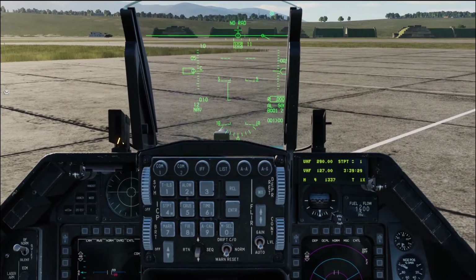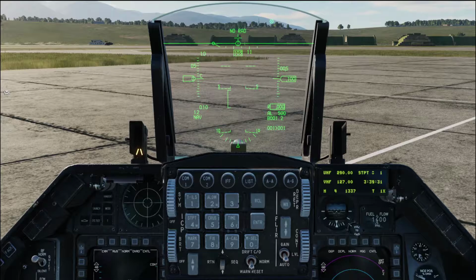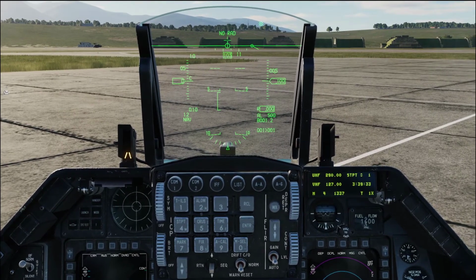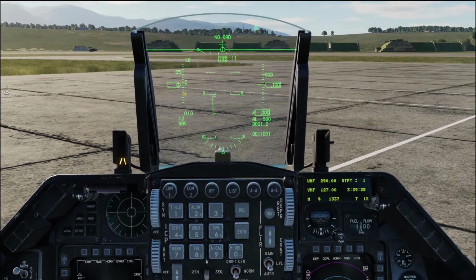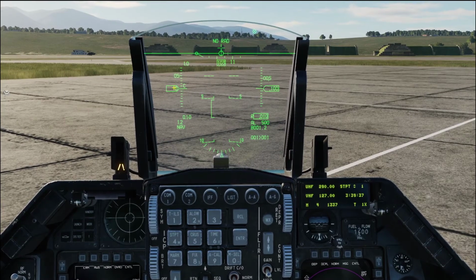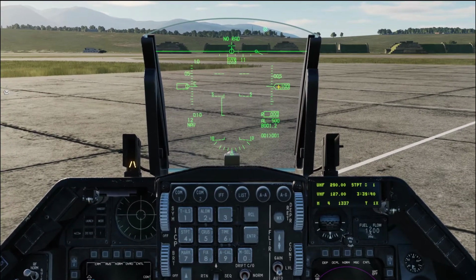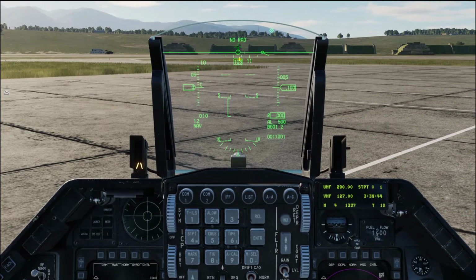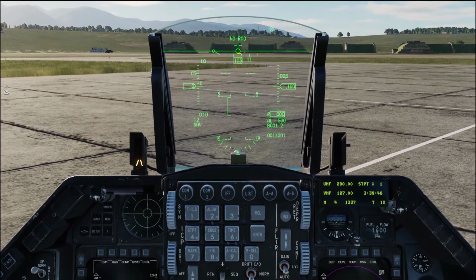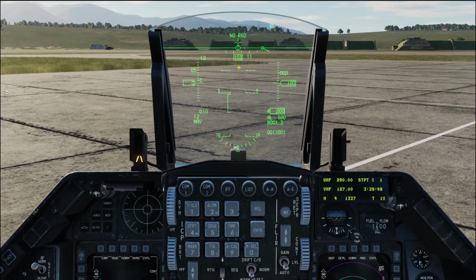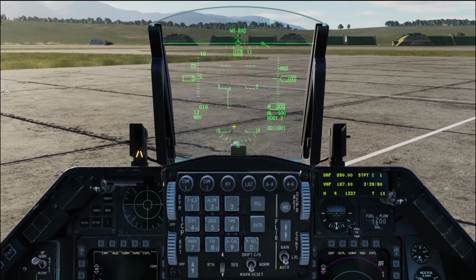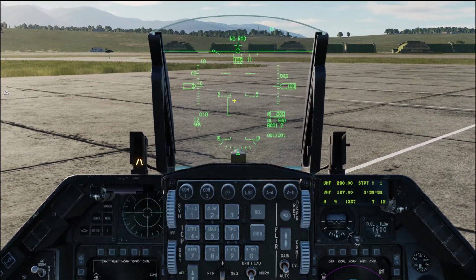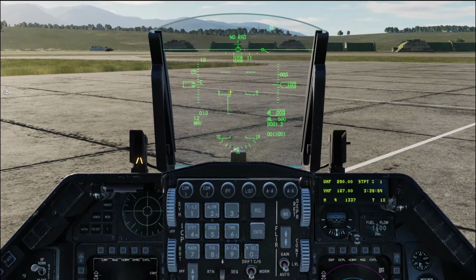Moving on to the left, we have the head-up display or the HUD. Generically speaking, the speed is indicated on the left side, the height is indicated on the right side. The heading is indicated on the top with the flight path marker, and the attitude bars toward the dive are in a dashed pattern, and above the horizon they are continuous lines.